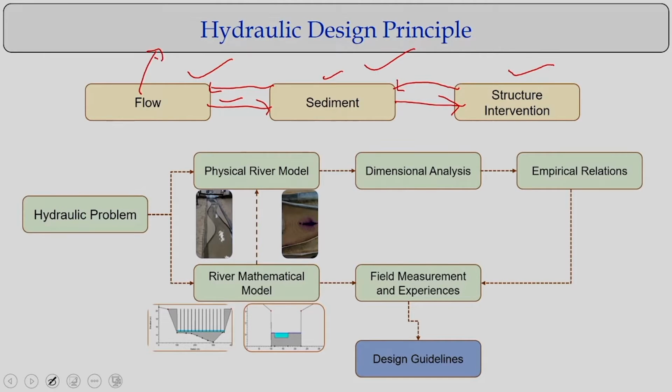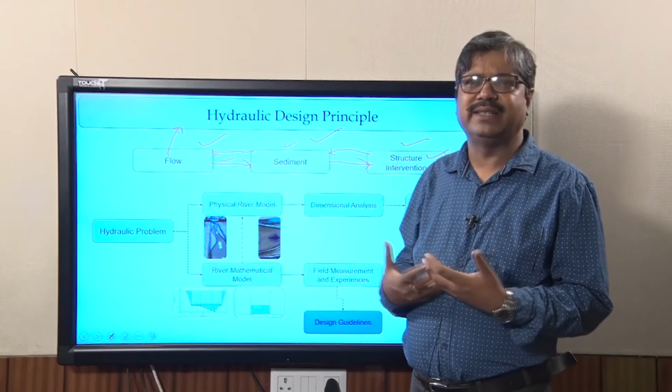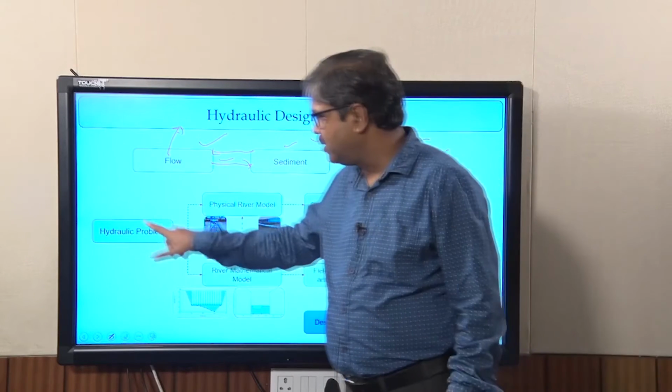That depends upon the structures, what type of piers we have, the size of the piers, the dimensions of the pier or the abutment. All are interacting with each other to determine the hydraulic design. That is the reason it is not an easy task. That is the way you do it.